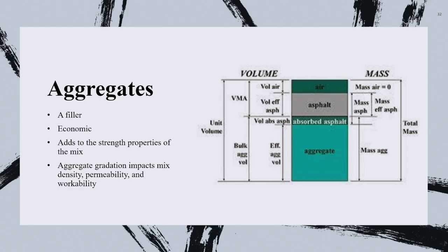And basically, there is a lot of testing. There is a kerosene test. I'm not sure if you do the kerosene test for your aggregate to quantify how much kerosene the aggregate would absorb, and this is an indication. It's indicative of how much binder your asphalt would absorb. If you don't do this correction before doing the mix design, you'll have on paper or in your mind a mix that is not there in real life.